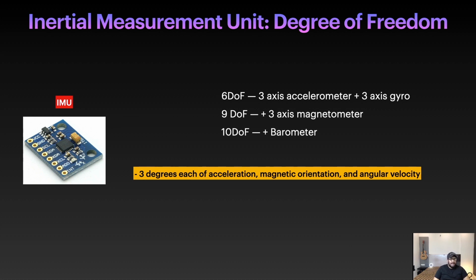That is acceleration in one axis; for roll, there would be different acceleration for pitch and for yaw. Similarly, the gyroscope helps you find the angular velocity on a particular axis. What is the angular velocity in one particular direction, let's say pitch? With the help of the gyroscope, you can measure that. And with the help of the magnetometer, you can find the magnetic orientation of your drone.